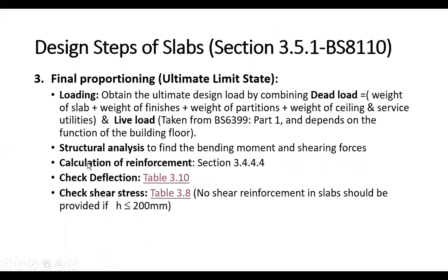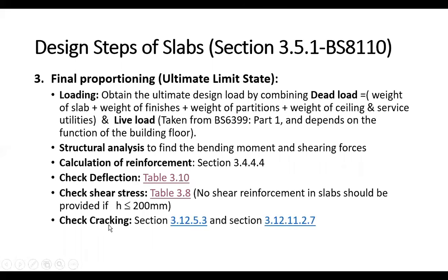Okay, so we calculated reinforcement, checked for deflection, checked for shear, and it is safe. We have also to check for cracking. We have to be sure that the cracking will satisfy the serviceability requirements. The BS code satisfies the cracking procedure by controlling the area of the steel reinforcement and the spacing between the steel reinforcement. So it is not telling you you have to check the crack widths and you calculate the crack widths. It's some like difficult calculations. No, it is easier in the BS code, and many codes are using the same method now.